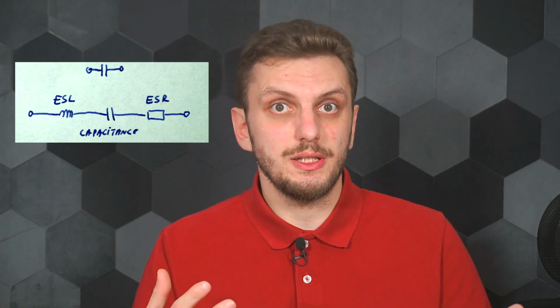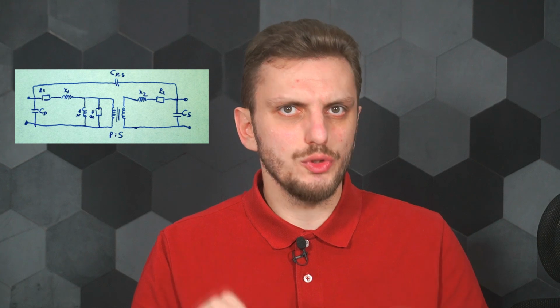So, the first thing you might ask yourself is, why? What's wrong with discrete components? Or in this context, lumped elements? Well, any component other than its useful property has some not so useful parasitics. Inductors have parallel capacitance, capacitors have series inductance, transformers have all sorts of problems, and even the humble resistor can run into issues under certain circumstances.